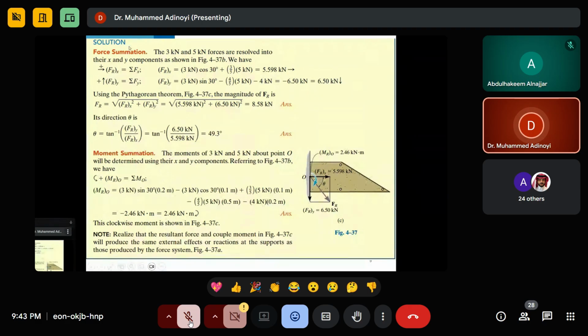So I just bring what we did before here so that we can have them on one page. Again, look at the direction of the arrow. This one is telling you that this is positive and this is the counter to the established y direction. Your established y direction is in this direction. Now the answer you are having is minus, so it means it is in this direction. There is a reason for this, so that when you go to show your forces, it will help you to know how to orientate the FR, the resultant force.